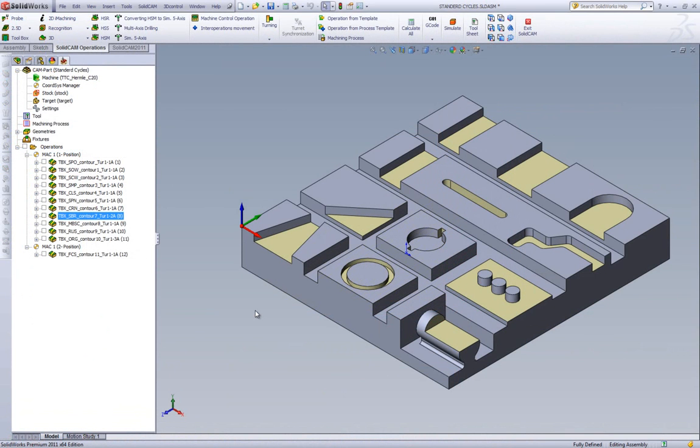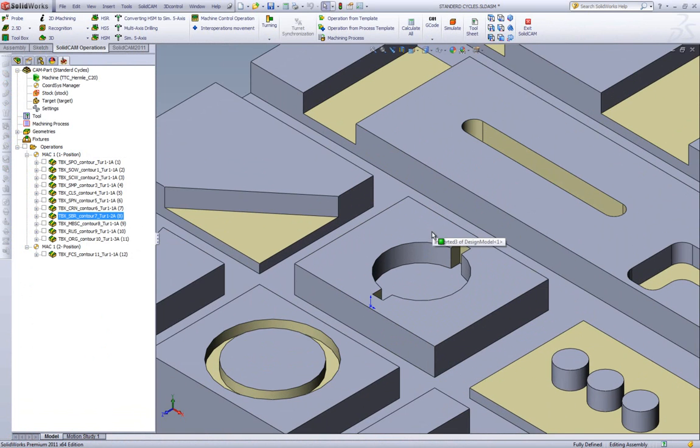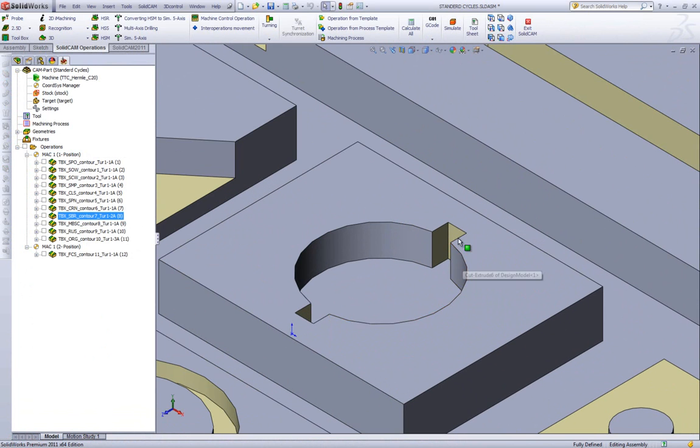The next option we have in Toolbox is broaching. If we have an area such as this, where I am able to actually do a broaching operation using my CNC machine. In this particular case, I have two areas where I want to broach. This one and this area over here as well.